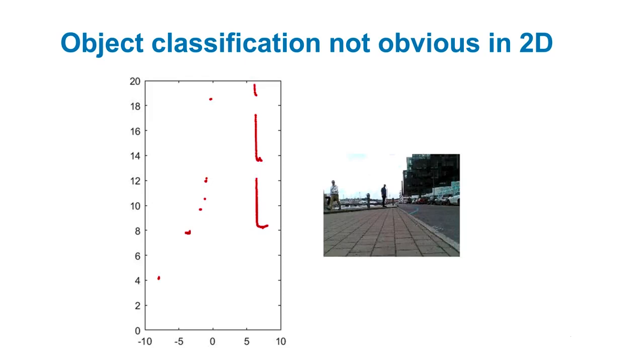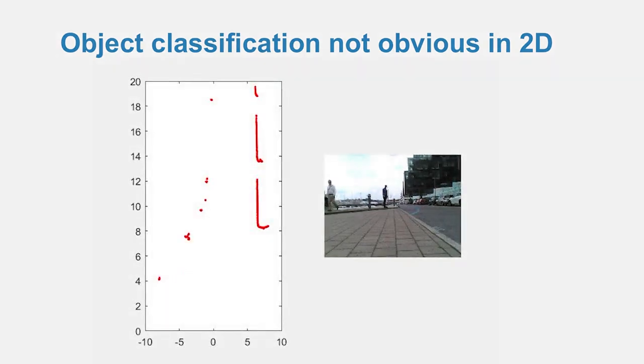Another aspect of 2D LiDAR implementations is that the type of information received is very limited. As seen in the right figure, the shape of the vehicles can be reasonably easy to identify, but without including object motion over time, such as measuring the frequency of leg movements of a person walking, it's basically impossible to differentiate between a pole and the legs of a pedestrian.